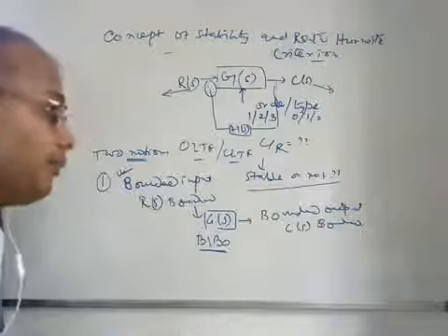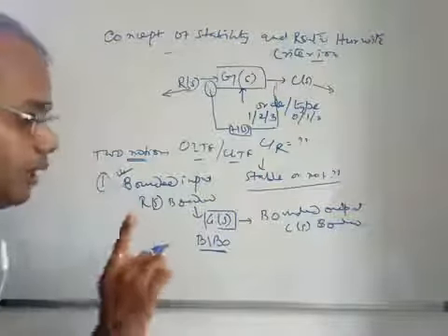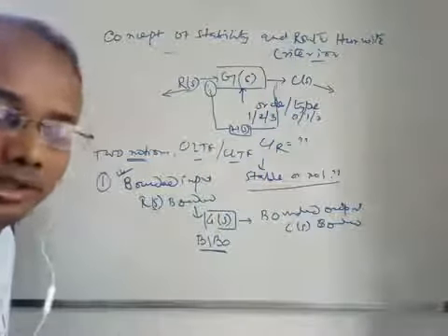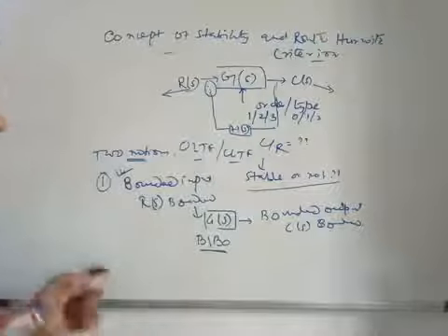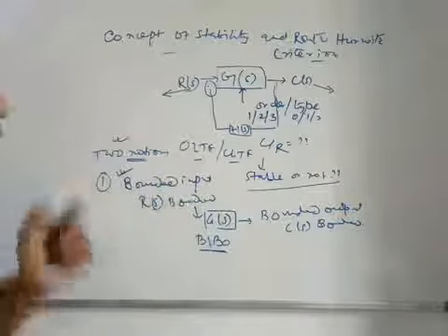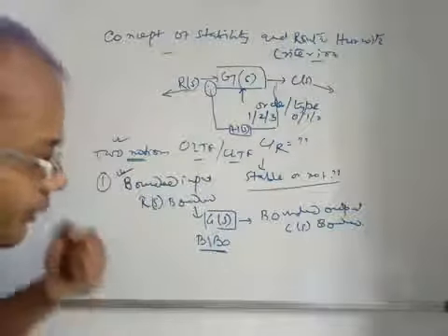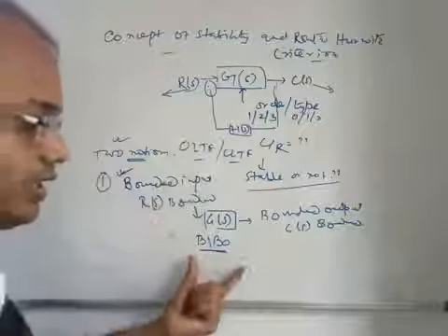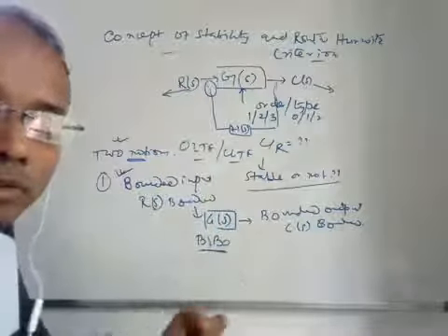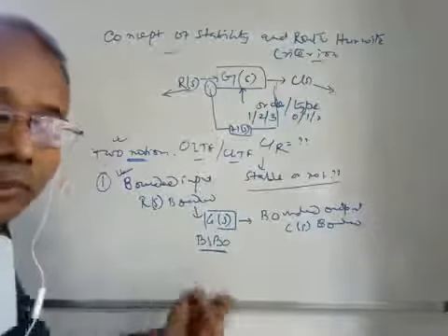But if you apply a bounded input and you are getting an unbounded output, the system is said to be unstable, right? So this is the first notion: stability can be defined like this, if a bounded input is applied to any system and you get a bounded output, the system is said to be a bounded input, bounded output system, that is the BIBO system.